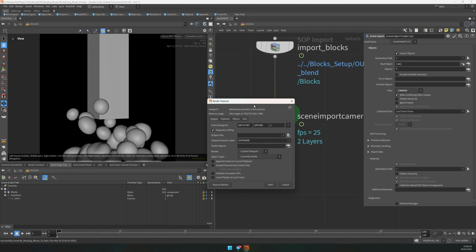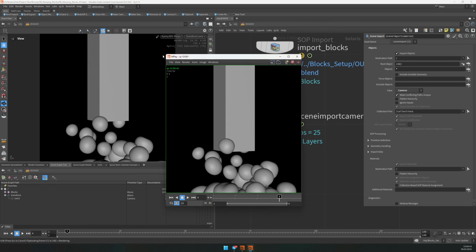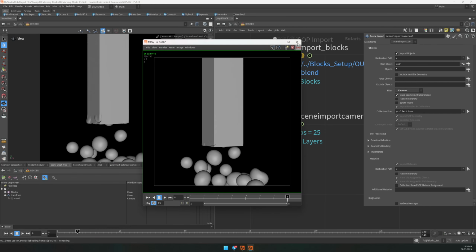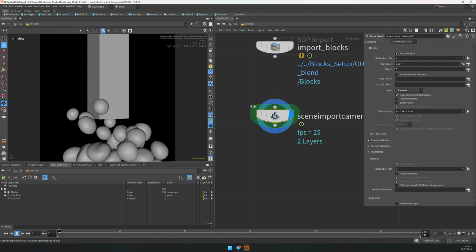If you don't want to render this to disk, you can use this flipbook. This is a quite nice feature that I found. You can limit frame time, for example each frame is going to render for only 2 seconds, then select the current beauty pass, and you can do a flipbook of your camera viewport, which is quite cool. But of course, I'm not going to do this. It's just a tip that I wanted to tell you.